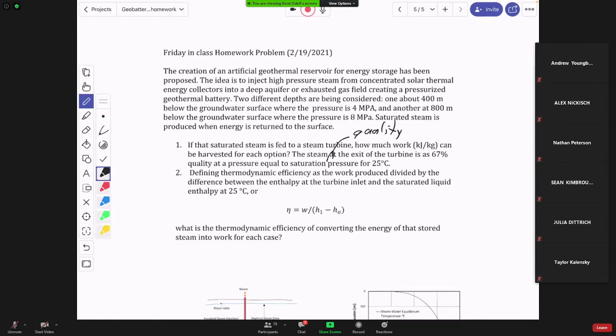These are all just opportunities for us to feel like we can go to the steam tables and it would have to make some sense, right? The enthalpy should be pretty high. And so you look at the steam tables and you look under enthalpy and you think, oh, this is the vapor enthalpy, saturated steam enthalpy, and you look at those numbers and say, oh, those are like over 2,000, all of them. That's a part of also getting some intuition. That's what those numbers should start to look like. And a lot of it is just looking at these tables and thinking about how they all relate, and how the internal energies fit with the enthalpies and how that all fits with the PVT information.